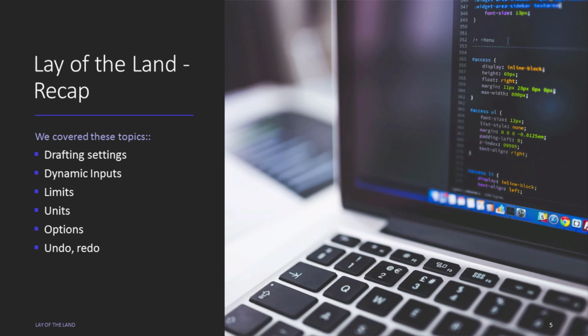And next we also looked into the dynamic inputs that are available to us and how we can move from the absolute to relative polar and henceforth, by using comma, at the rate of, angular and pound symbol. By this we can also get a floating tooltip of what is expected next out of that command. So those come in the dynamic inputs.